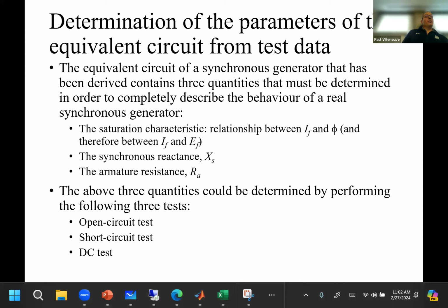The problem with doing things at frequencies is that as you sweep the frequency along, are you actually operating the equipment at whatever frequency you specify? So you don't always have really good results when you do things at off nominal frequencies. We're going to do very similar approaches, but we're going to add one additional test, which we'll call the DC test. We'll add that into our electric machines.